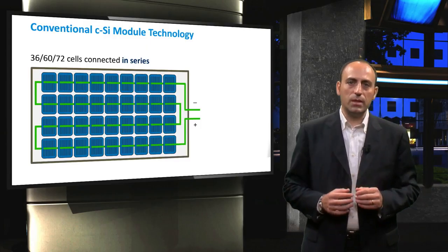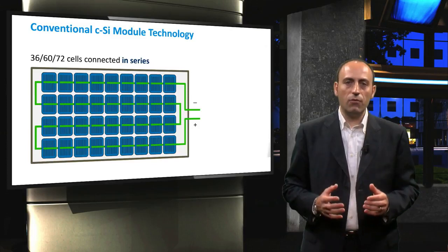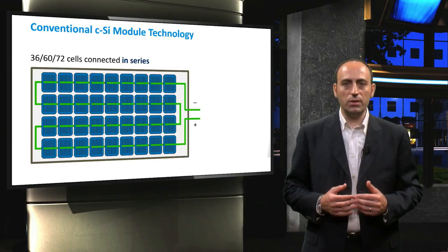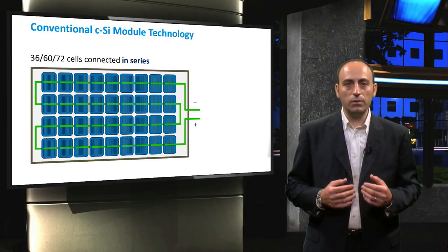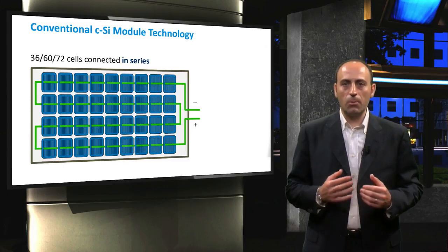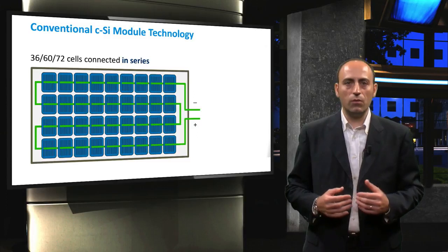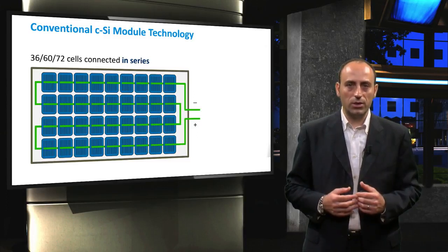For some PV systems, the right solar cell configuration depends on the application. For example, if you have a module with a high open circuit voltage that is close to the load voltage, then you may avoid the use of the DC-DC converter, which has some conversion losses. So the voltage and the current output of a module can be partially tuned through the solar cell interconnection.